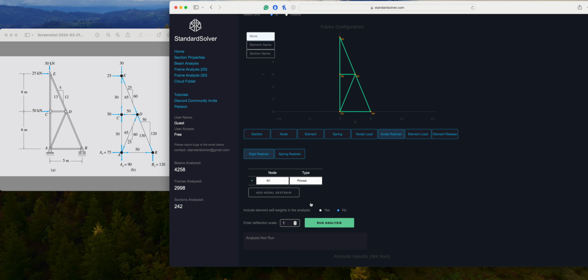Okay. So this being a truss, we want to have pin joints between elements. These are rigid connections. So earlier we used to release each element, which used to be more time consuming. Now you can release it in different ways with this new module. What you can do is release nodes. So then you get this green symbol.